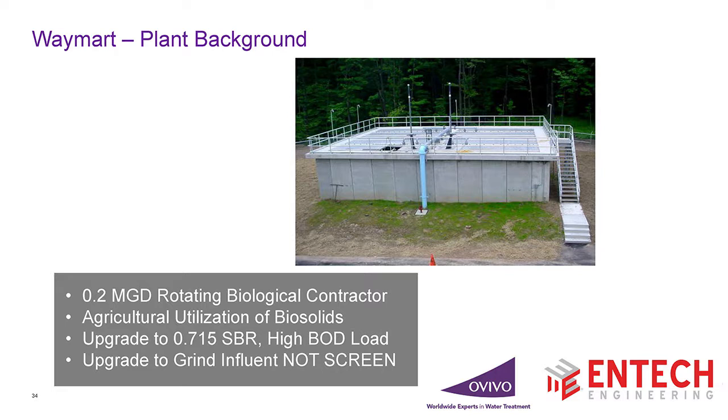We did not, and this is again another important thing, we did not screen our influent here as a cost-saving measure. We just used influent grinding to minimize solid size. So these digesters did get a lot of the trash from the wastewater, which eventually ended up in the digesters. Next one, Brian.